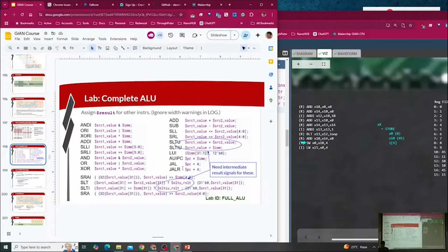Here's the destination register for JALR, jump and link register. The register part says that the address we're jumping to, the base address, is coming from a register versus coming from the PC. In either case, we want to link the program counter for the return. So in either case, we write the destination register with the PC of the jump plus 4. That's the return address.